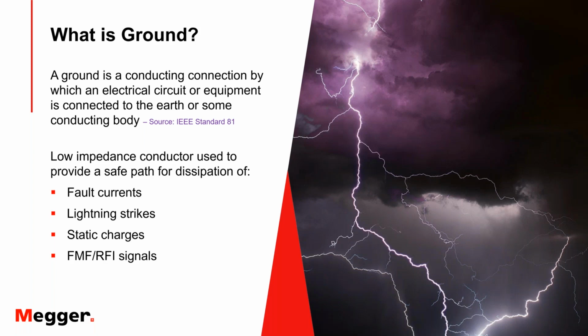So a good ground is there to divert these currents that you don't want going through your electrical system. You want them going back into the soil. In the case of utility faults, they go back to the transformer that generated them in the first place. In the case of lightning, of course, the charge evens out between the earth and the sky. Okay, next.